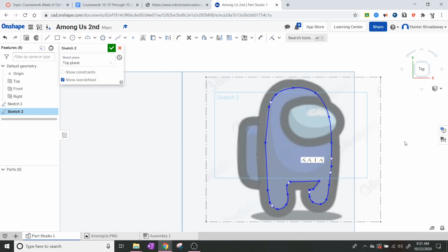No, you don't have to use the spline tool if you don't want to, but you need to make sure that they actually do connect, because whenever we try to extrude it, you're going to want to have that there. Some interesting stuff is going to happen now though, because if we use the offset tool down here on the bottom part, if I push this sketch out and I push this sketch out at the same time, they're going to hit each other. So that's going to be a little bit of a problem down on the bottom.